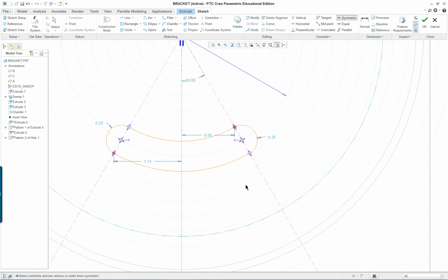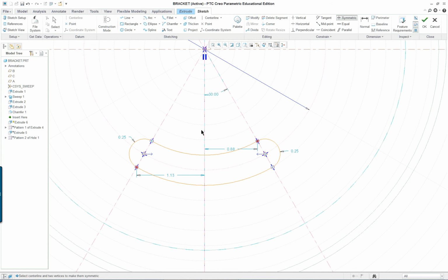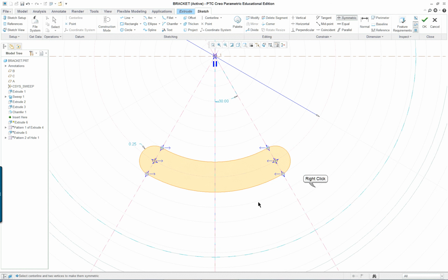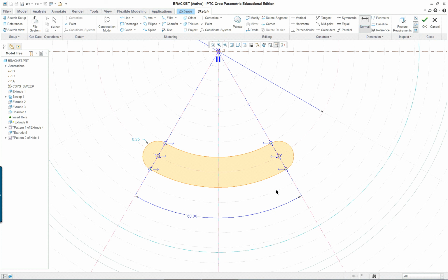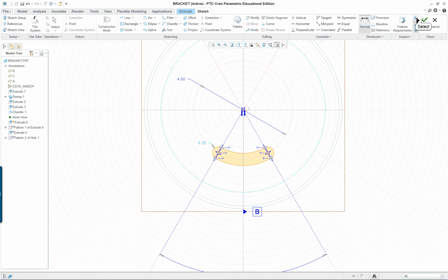So you want your included arc for your size here, and you want the proper dimensions over here. Some of these are extra, you don't really need them all. You could actually continue on with symmetric and use the endpoint for all of them, like so. And you're controlling it, and then if you want it again, you could do your included angle here, like so. So it makes it very simple dimensioning wise. I'm just going to use the sizes that are there. Give a check.